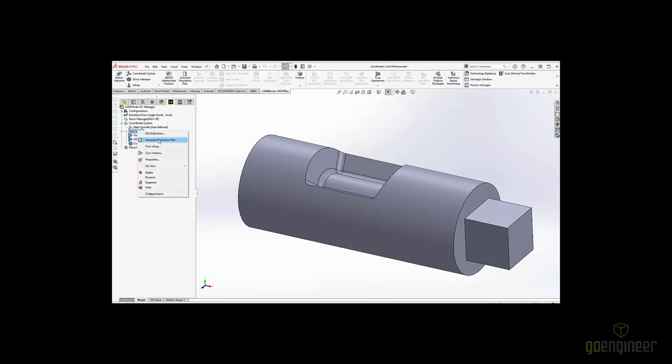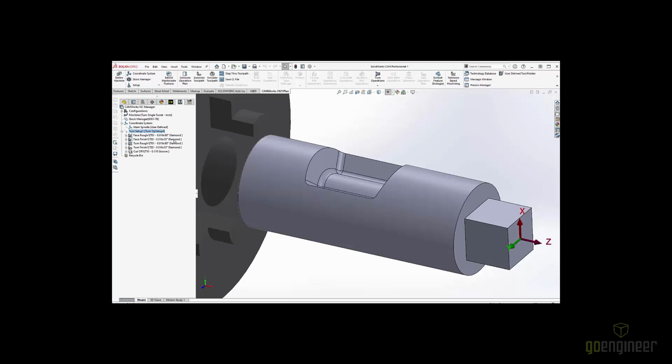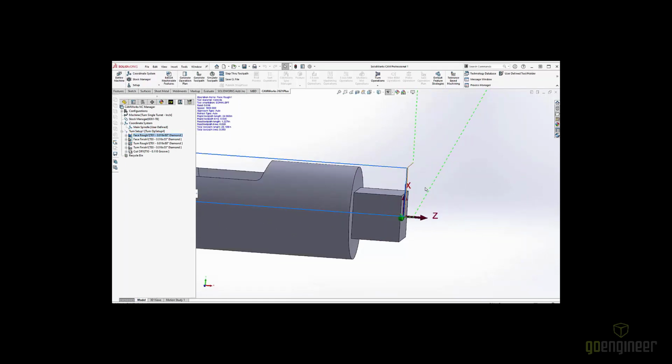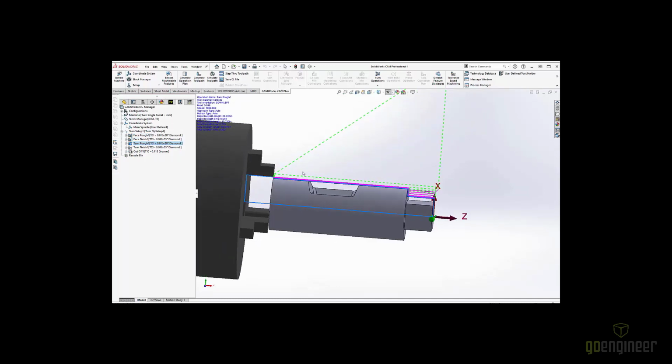Now, once again, I can get my toolpaths back very quick with Generate Operation Plan. These are customized strategies, once again, so I can have these all preset, programmed the way I like to do it, that I know is safe, effective, gives a good surface finish. Finally, generate toolpath for all that. We see that preview of toolpath on the screen with a face rough, face finish, some OD rough and finish.